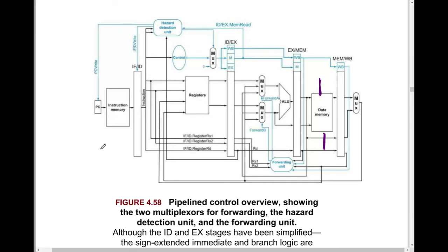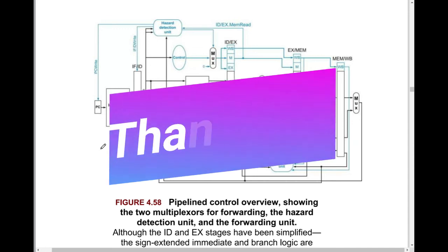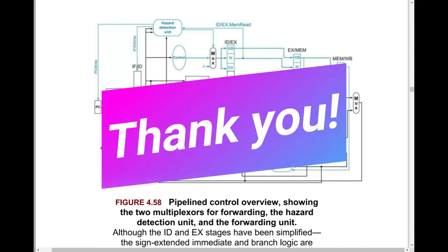So this data path that I'm showing now is the complete data path, including pipelining, including the forwarding unit, and including a hazard detection unit. This diagram is complete, but it has no control signals to handle control hazards. So in the next class we will discuss how control hazards can be handled in a pipeline in this data path. Okay.